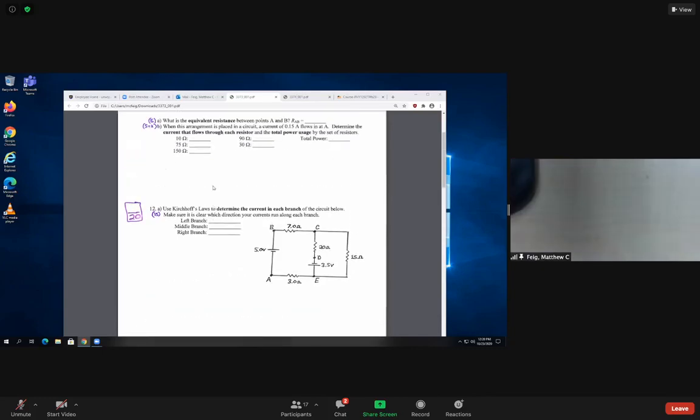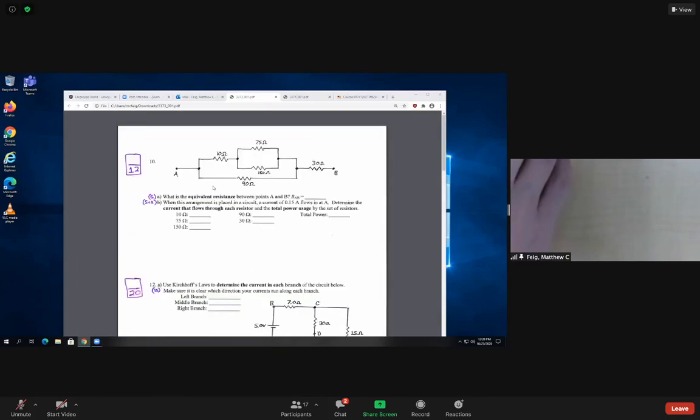Did you have a question about the previous one? Yeah. Sorry, I should have said, is it easy to tell if the resistors are parallel? Looking at the resistor with 10 and the resistor with 90, would that count? That wouldn't count as parallel, right? If you do a calculation of 1/10 plus 1/90, reciprocal, that won't represent this circuit, because those two resistors are not in parallel. Eventually, you can say something about 90 ohms being in parallel with the entire top combination. That would work, yeah. Okay. I was just double checking.